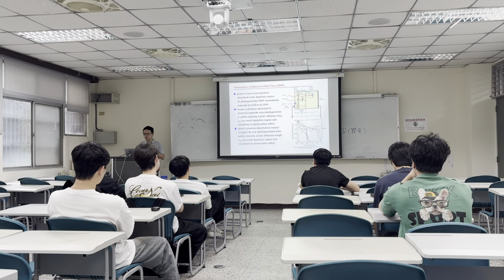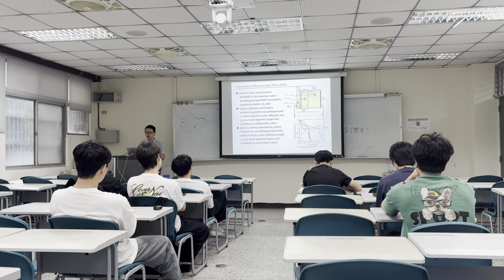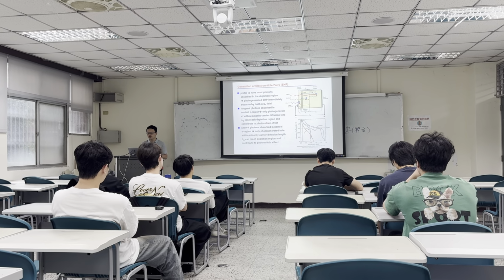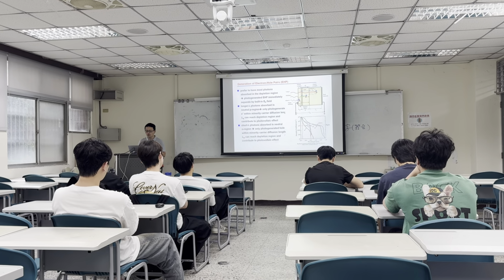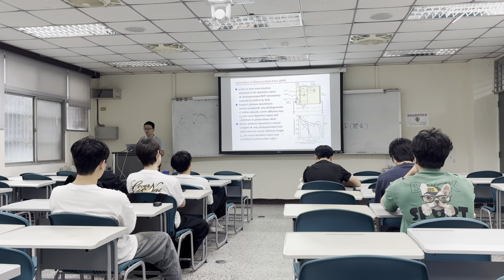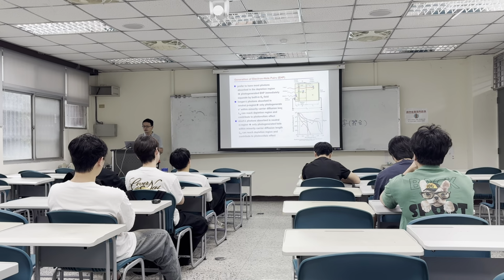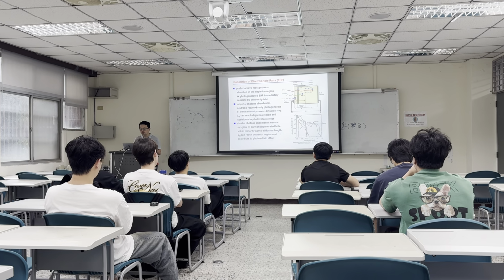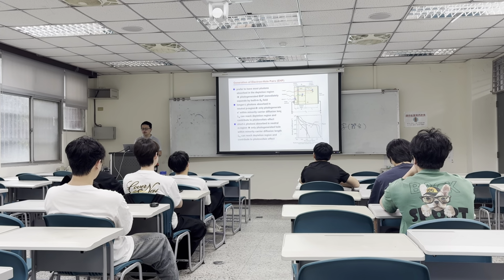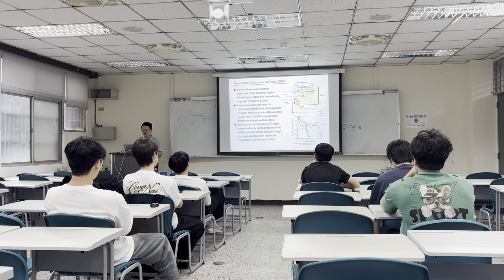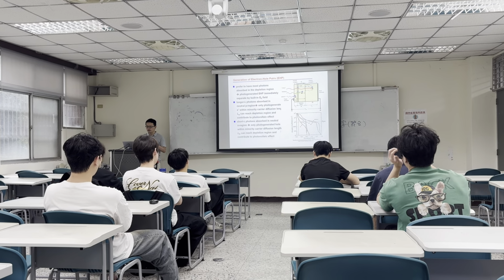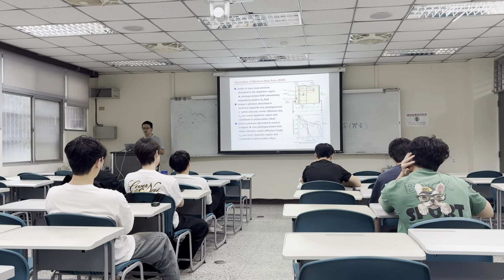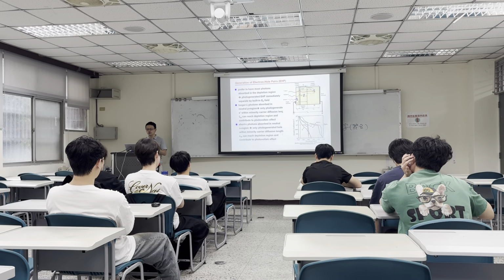So the effective region for the silicon solar cell is actually within the range made by the hole diffusion length in the N region, the diffusion width, and the electron diffusion length in the P region. So that is actually the effective area for the silicon solar cells to absorb the incident photons to generate the electron-hole pairs.